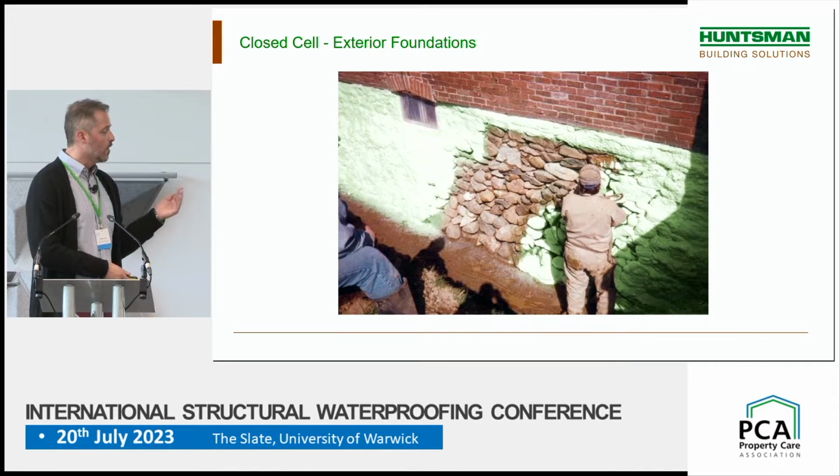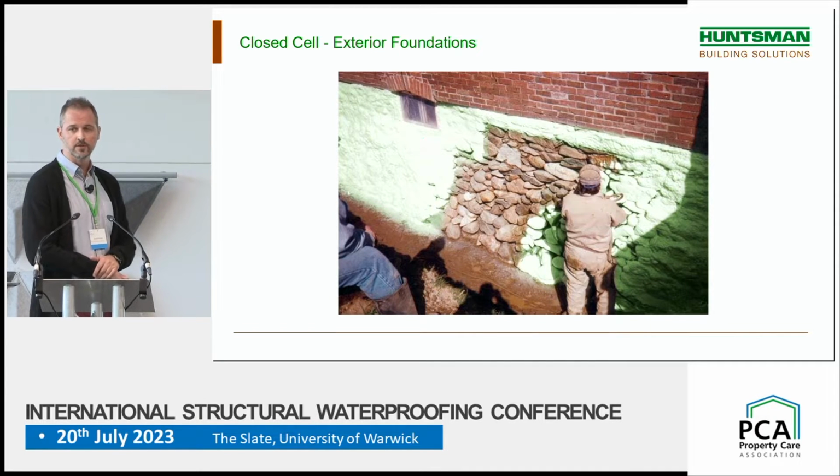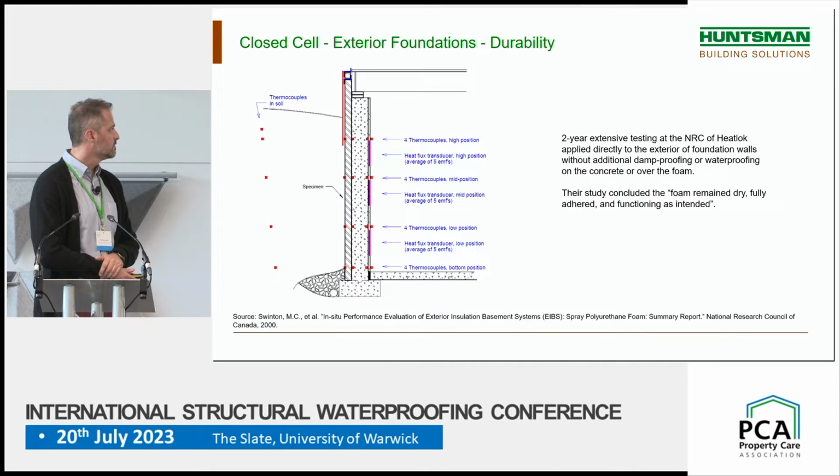Same thing for old foundation or stone foundation. This is the perfect product for these types of foundation because of all the gaps and the unevenness of the surface. Other insulation products would be hard to install for this application. So with the good adhesion of the spray foam filling all the gaps and cracks, this is the perfect solution for these types of foundations.